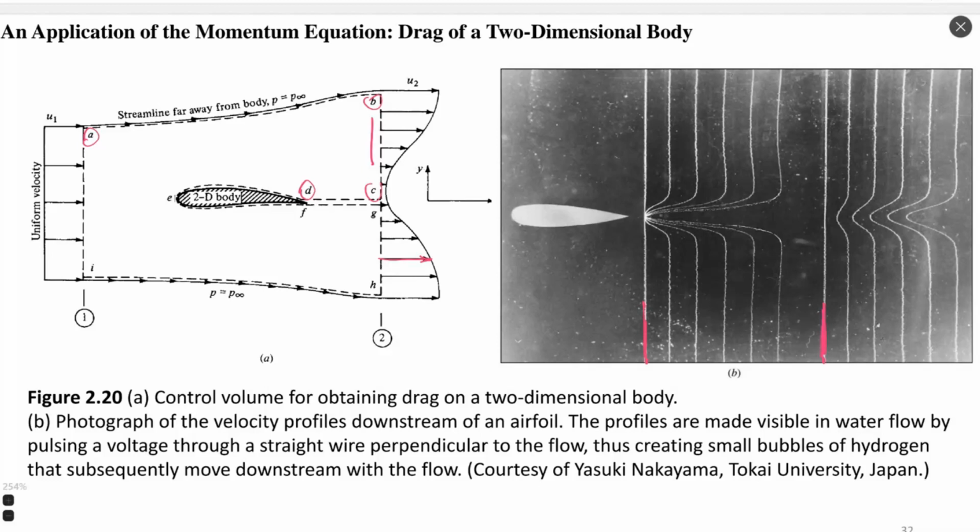from the end of the maximum coordinate of the control volume to the trailing edge of our airfoil. Then line DEF is describing the shape of the airfoil. It is on the airfoil, inside the flow. It's not a line on the body. It occupies the same geometry as the body geometry, but we consider this still inside the flow. Okay, it repeats the geometry of the airfoil.